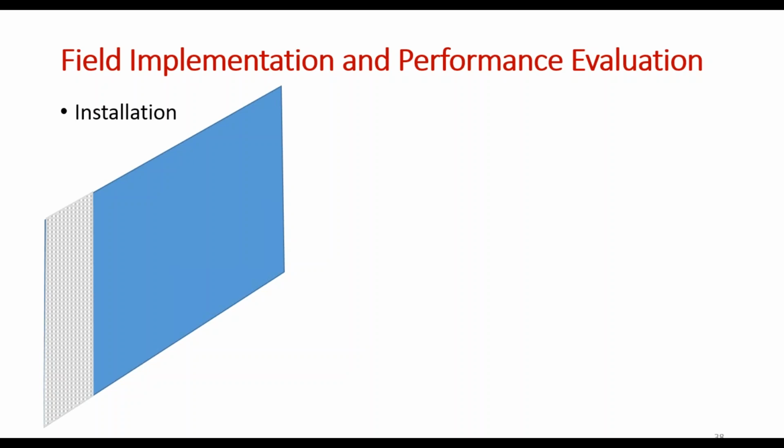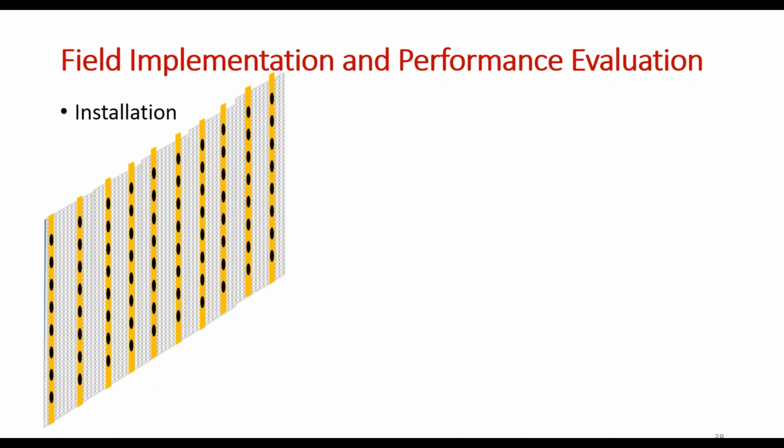You can use concrete nails, or you can get some help from wood battens. So the way they did it is they have the wood batten, which passes the whole length, and then they nailed it, and then they do one more course, and then they cover the whole wall. So this completes the drainage system.